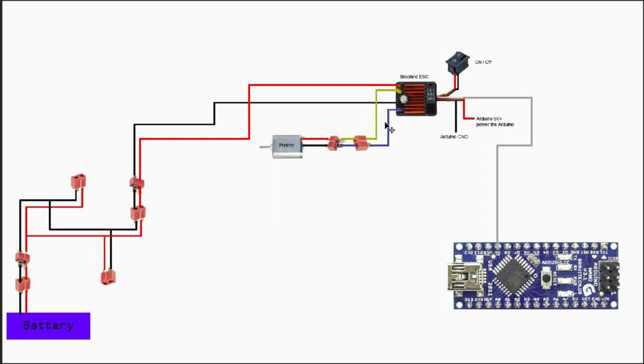So again, why do I choose this ESC? Because I believe that it actually makes the circuit easier to implement. In a way, you have less thing to solder, and it's pretty straightforward. Receive power, supply power, control the ESC through Arduino.